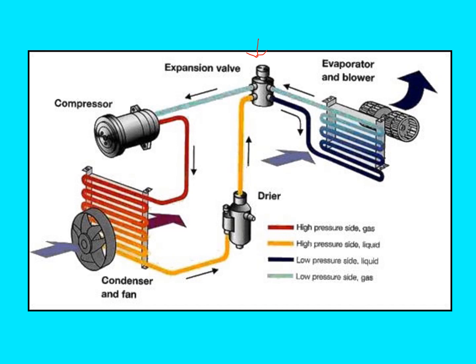So again, you can see the compressor is running. If the drive plate right here is turning, then we're moving the refrigerant through the system. It's being pressurized, so that refrigerant is moving as a high temperature, high pressure vapor into the condenser, with airflow across it. The condenser is going to be hotter than the ambient air. So the refrigerant is going to give up its heat to the surrounding air and condense into a liquid.